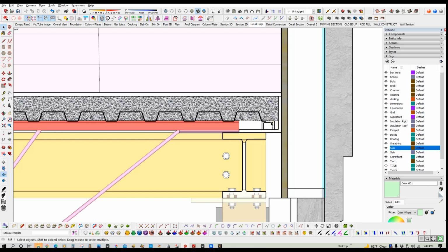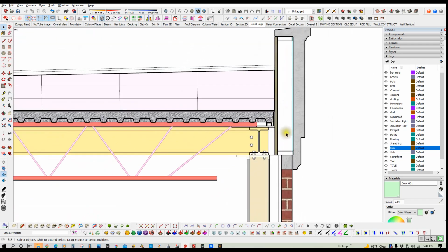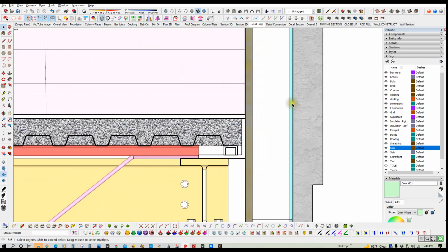Basically, I'm addressing the situation, telling somebody they need to put something there. The rest of this is metal studs for the parapet, plywood sheeting on the back side of that parapet. So I have to sneak it down through behind this angle, or the order of things might have to be considered here. The little blue stuff here is the insulating sheathing.